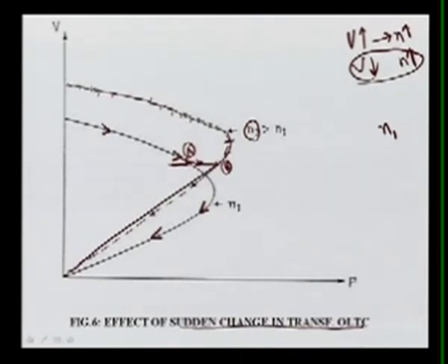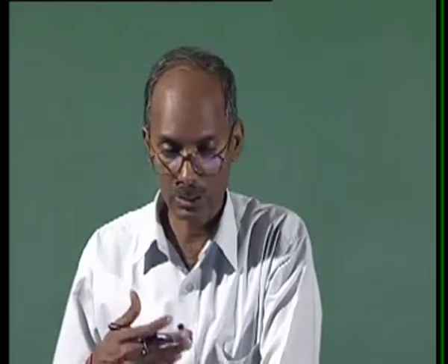zone, and once it has landed here, it keeps on reducing and finally your voltage will go to 0 and your system will collapse. So this is also one concept. It means OLTC transformers sometimes try to improve the voltage, but sometimes they also give the voltage instability case.